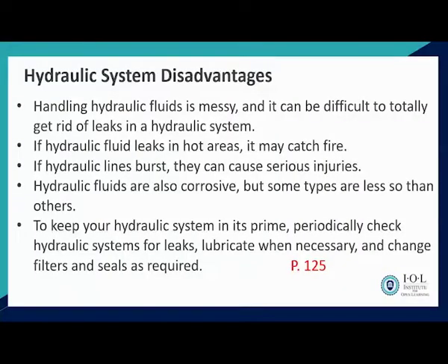However, hydraulic systems also have disadvantages. Handling hydraulic fluids is messy. It can be difficult to totally get rid of leaks in a hydraulic system, so we may have leaks of oil, which may be messy or dirty to handle. And if hydraulic fluid leaks in hot areas, it may lead to fire.